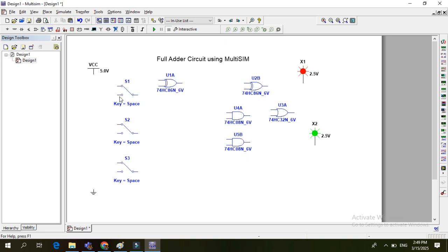These 2 points are connected, meaning they are the normally closed points. One point is not connected, so that one is the normally open point. When we click on the switch, it will change its position and be connected with the power supply. This switch works exactly the same as the switches used in our houses. We have given this power source input, and now the NC connection we will connect with the ground.